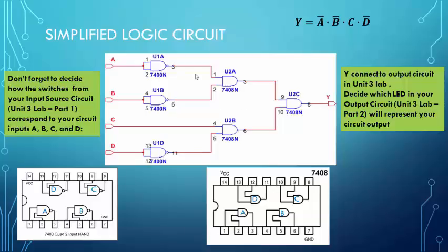After the AND gate over here, you should get A' and B'. After this AND gate over here, you should get C and D'. And then you put another two-input AND gate that will AND this group and this group together.